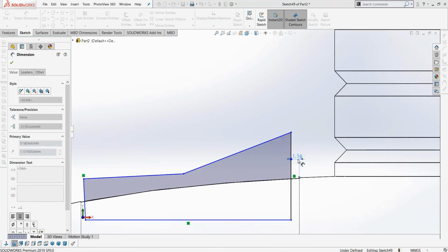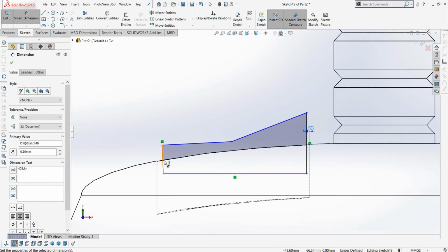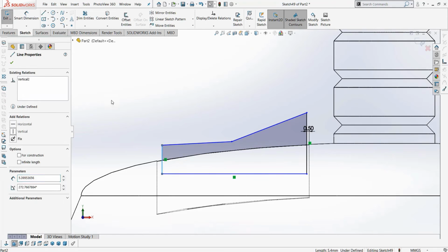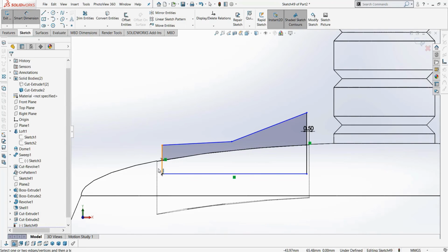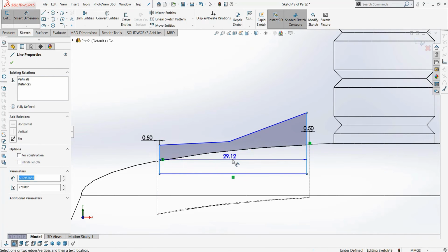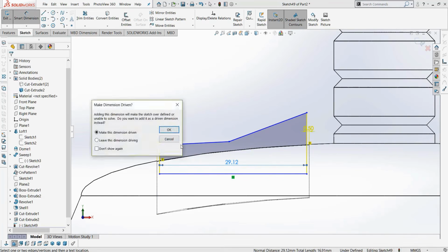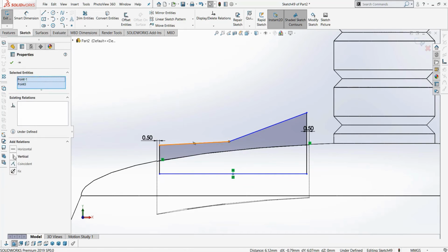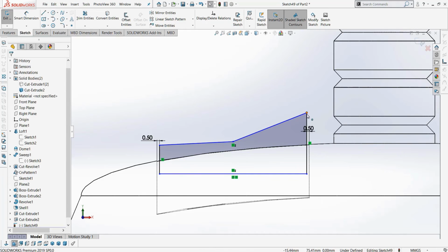The distance to this corner is 0.5 millimeter. First, I'll take this vertical relation to make it completely vertical. By vertical, I mean the two are relative to each other, and the distance between them is 0.5 millimeter. The other one is 29, and we can't measure it anymore. Then, it was completely correct for the center of this to align with this one in a vertical line.